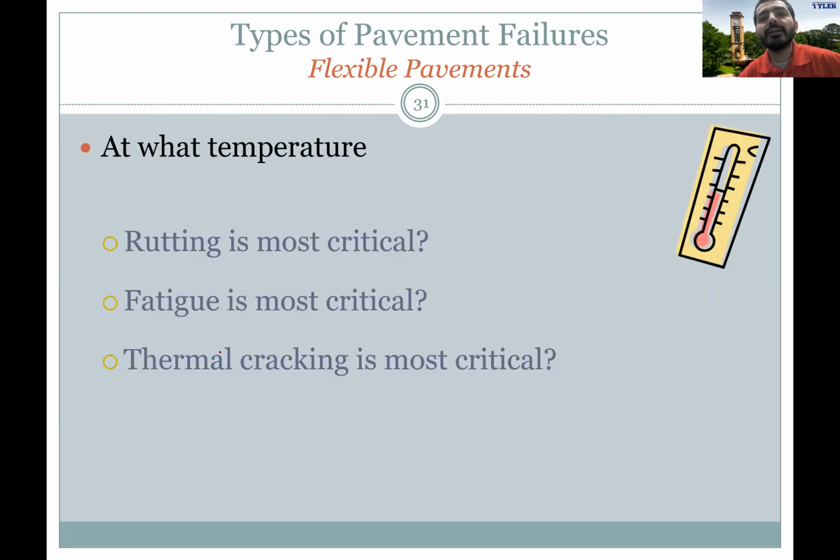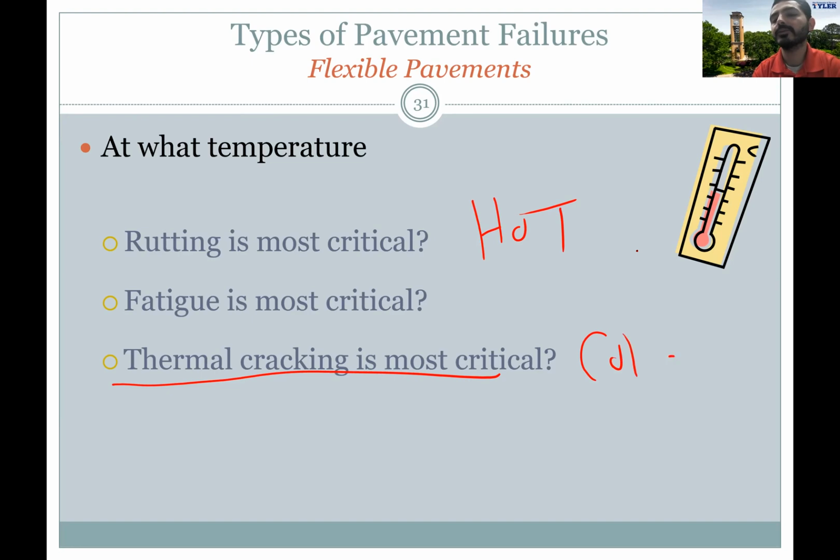All right, so in general terms, at what temperature does rutting happen? Rutting happens at hot temperature, whereas thermal cracking happens at cold temperatures, and fatigue cracking can actually happen at any temperature.